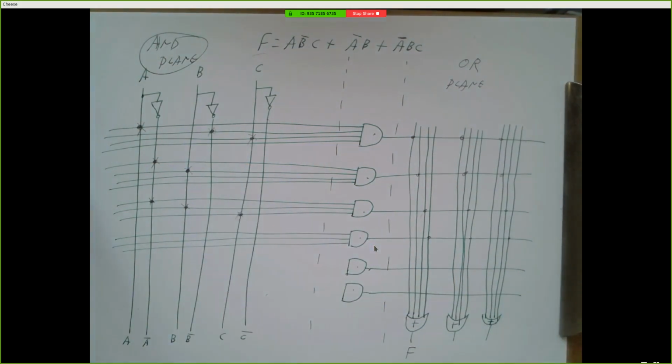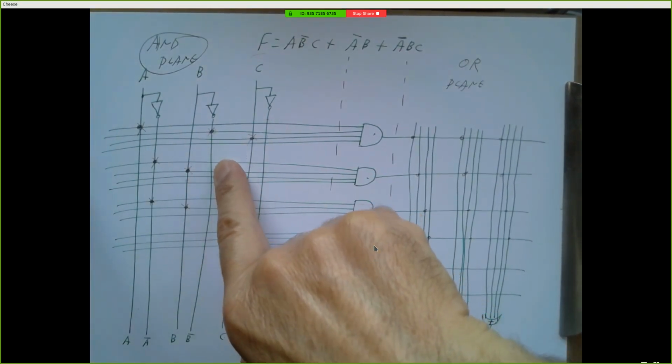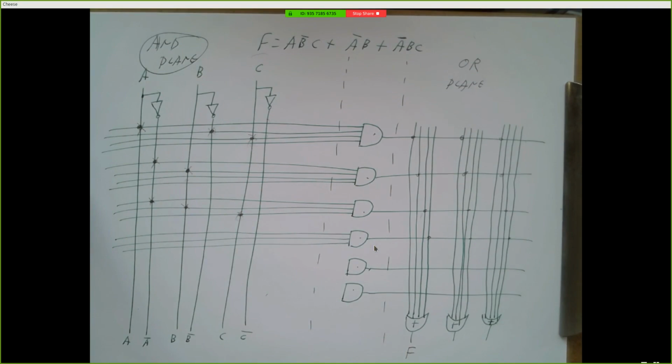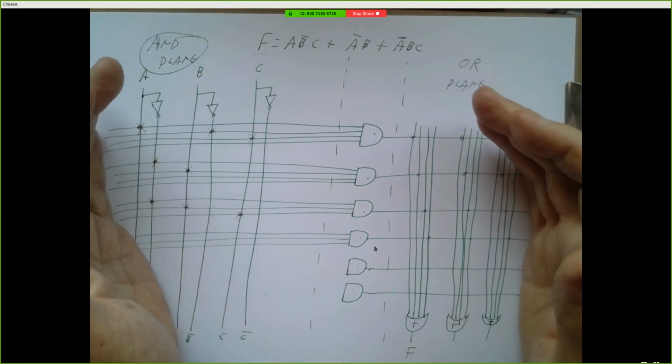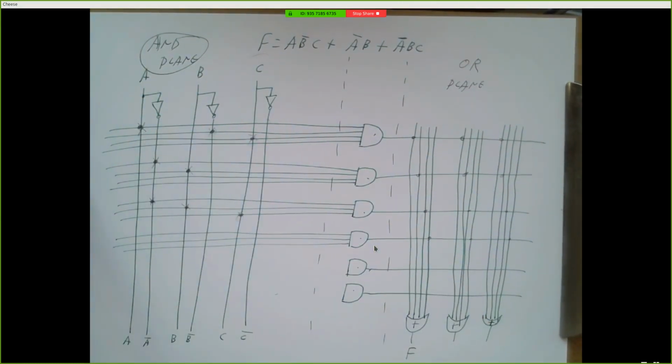We use more bizarre stuff that's based in quantum physics and such. And with this newer technology, it's possible to replace these fuses once you've blown them, right? To restore these connections. So we can do what's called erasing the device, so that we can put it back to its original factory state where all the connections are intact, and then we can get rid of the ones that we don't want.